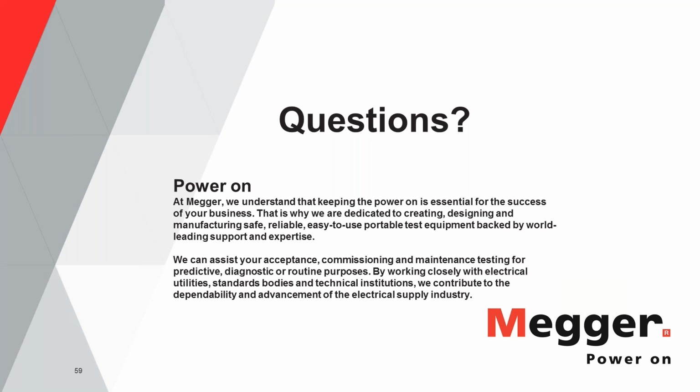So the pickup value could be set as a percentage or equal to the rating of the plug, and then the test current needs to be twice the pickup value. In the example that we discussed, the pickup value was equal to the rating of the plug, and the test current was selected as twice the pickup value, or twice the rating.